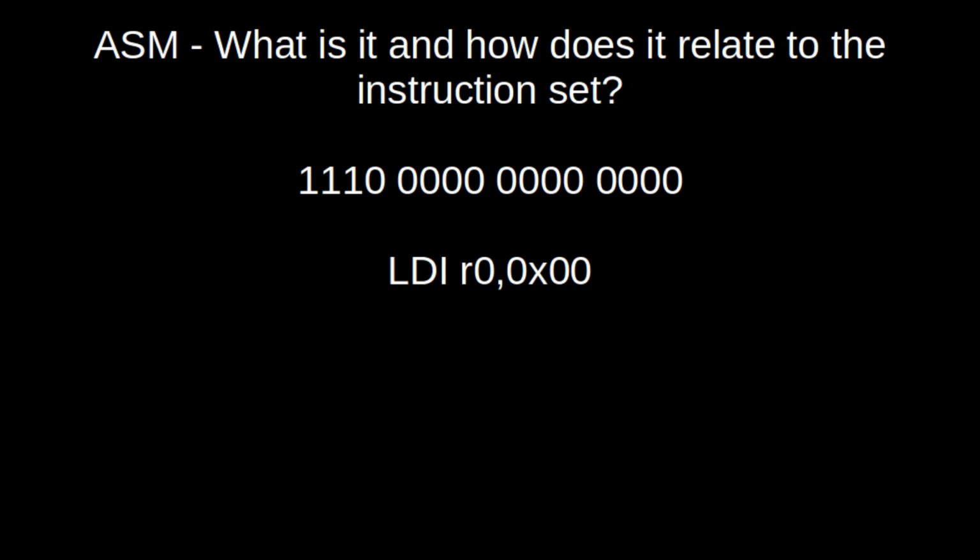So the ASM commands, such as LDI, are just English-type versions of the opcodes built into the microprocessor. The same important note remains, however. Each ASM command is performed in isolation. The microcontroller doesn't remember anything from one command to the next. There are other portions of ASM that are not opcodes. There are assembler directives that tell the assembler how to handle the code, or that make it easier for you to understand your code or change it later.